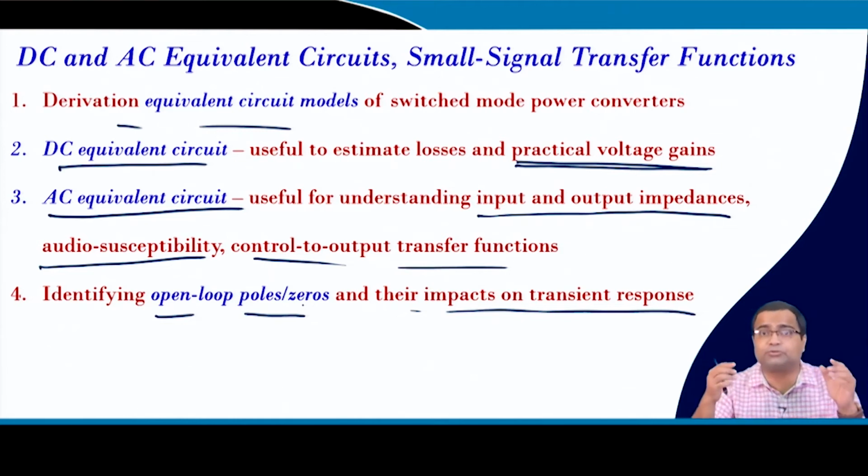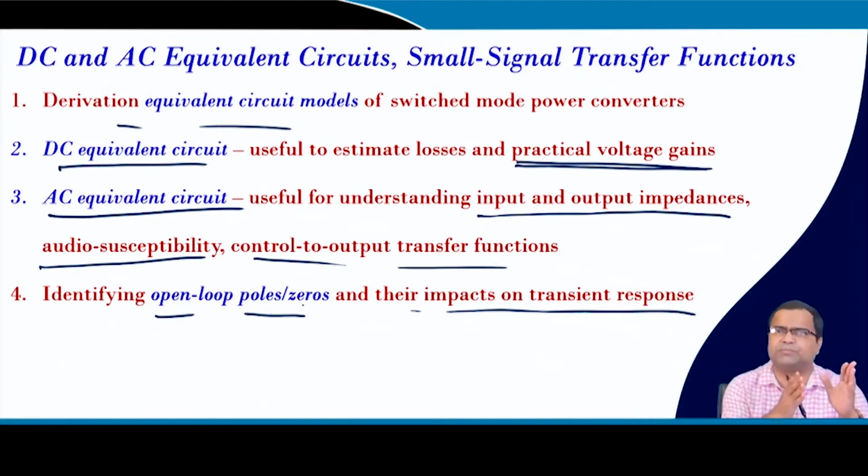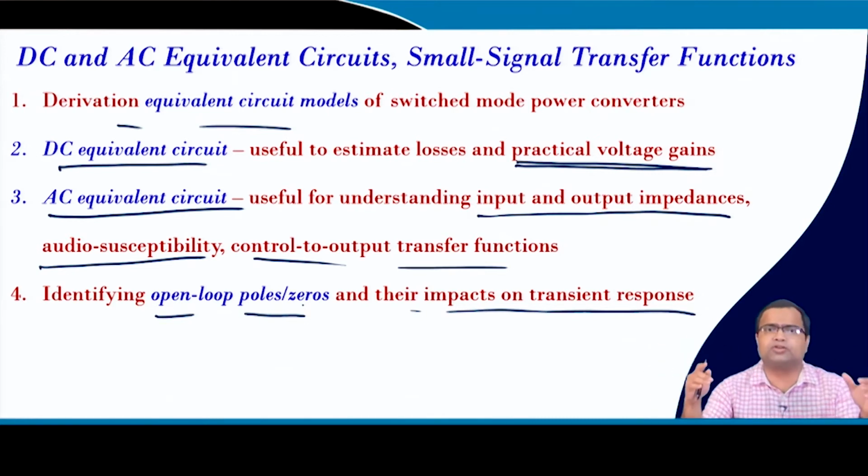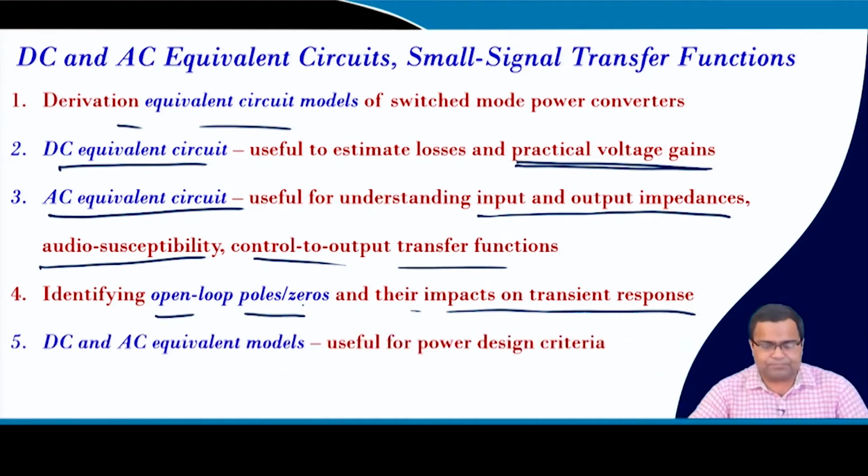And we also discussed the right half plane zero, which will introduce an undershoot, an inverse response, and that can significantly affect the closed loop performance. And we also discussed that if the right half plane zero comes close to the imaginary axis, then your closed loop bandwidth will be severely restricted because of the non-minimum phase behavior.